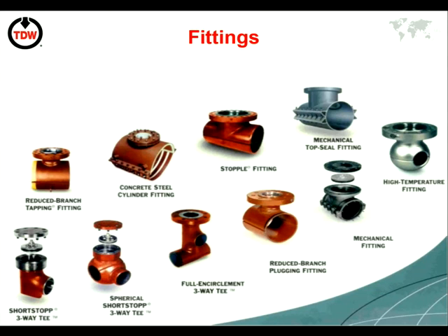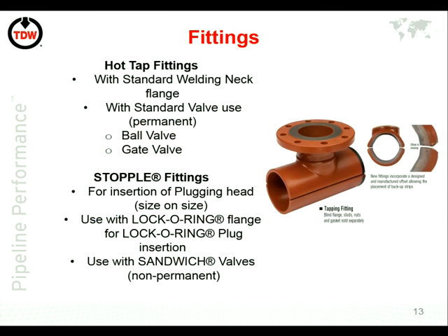As mentioned, these are the fittings themselves. So obviously, as you can see, this is the pipeline diameter, which would straddle over, and this is actually the tap diameter. So that's the hole size in there. So we can do what we call pipe on pipe. So if it's a 24-inch pipe, we can do a 24-inch drill in that. But obviously, what that means is that hole is 24-inch diameter. You obviously can't do bigger than the pipeline diameter.